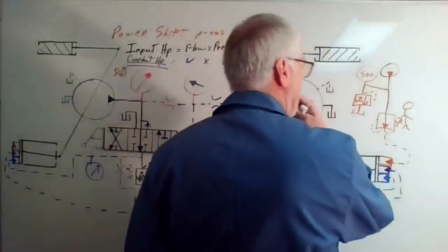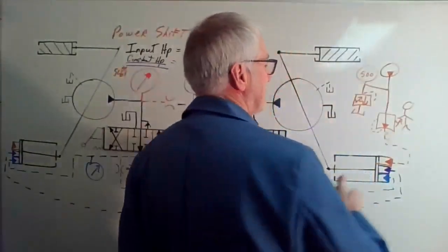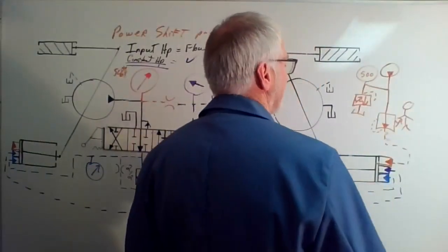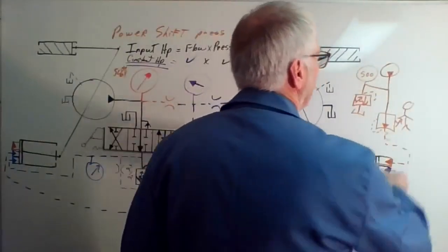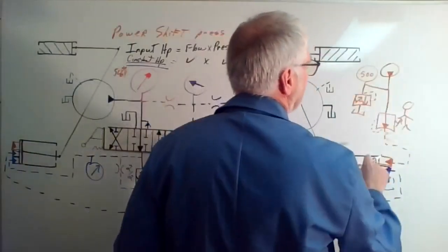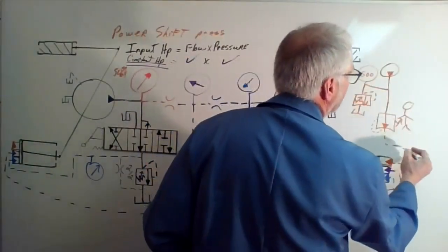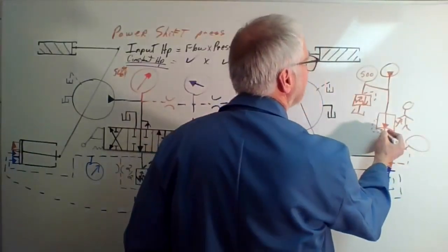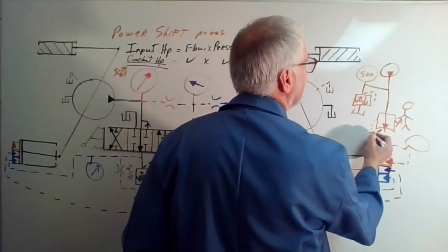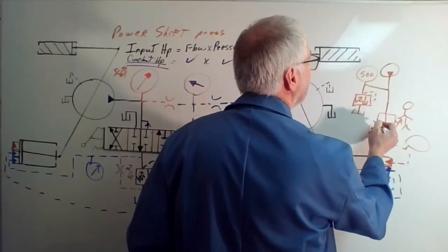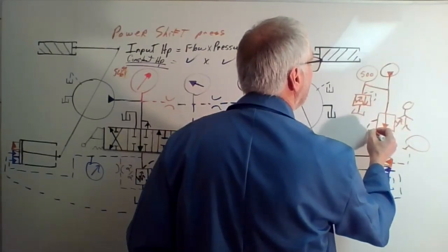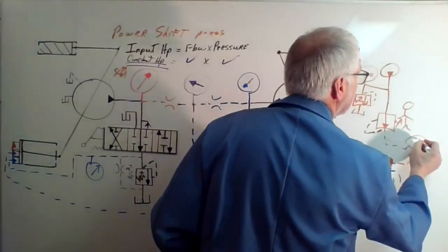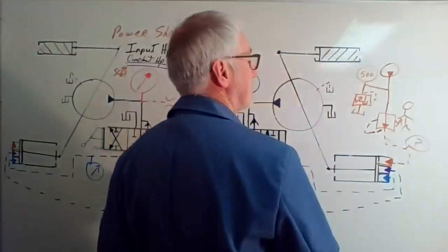so a normally open valve, a pressure reducing valve for all practical purposes, where the operator becomes a spring tension. Pressure regulated feedback as well. But let's just keep it a pressure reducing valve. And I would be able to control this pressure downstream of this valve, because this valve actually senses downstream of the valve to physically control it. So if I sense downstream, then I can control this pressure.